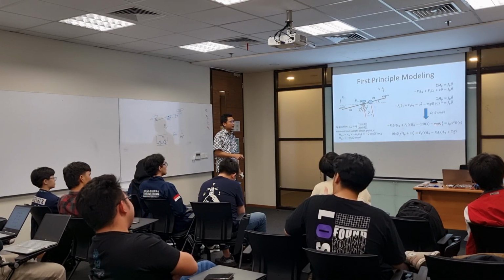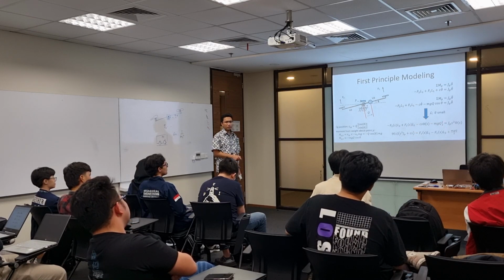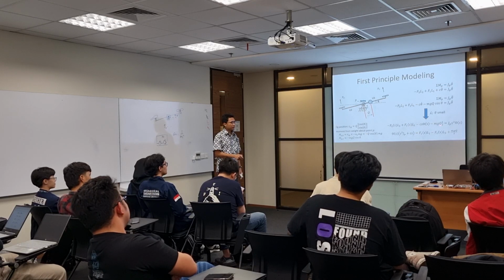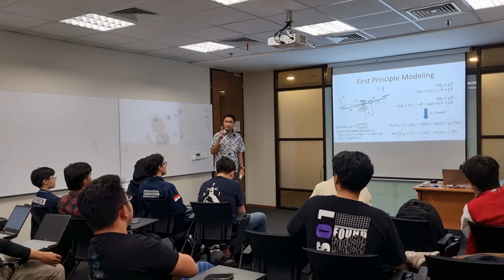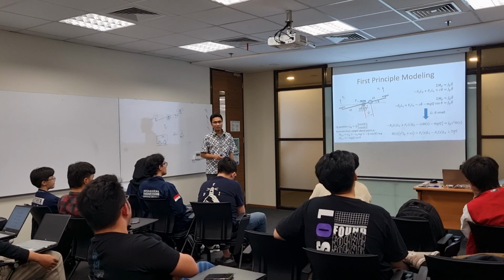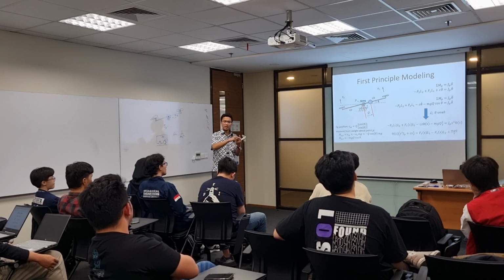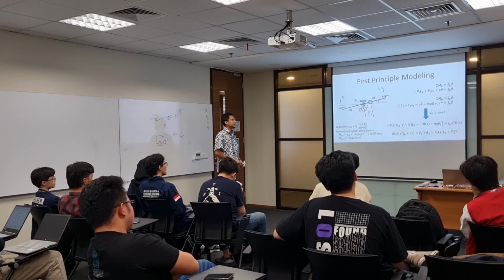So when I convert it into the Laplace domain, I just have the 1 over s over there. Anyone have a problem with this? We assume theta is very small, so cos theta for a small theta is close to 1, and when you convert 1 into the Laplace domain, you have 1 over s.